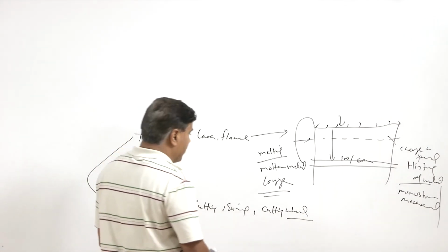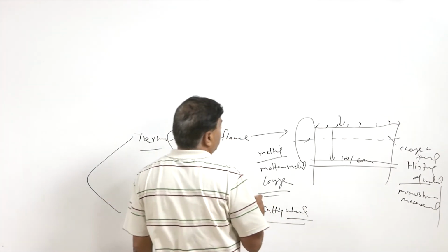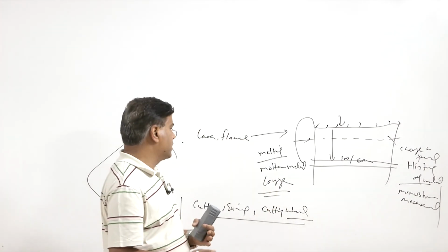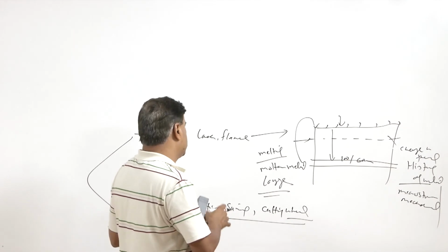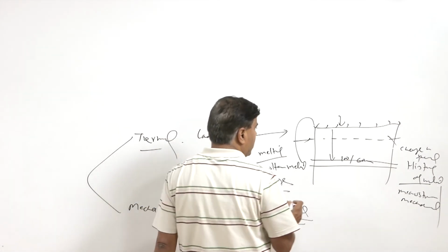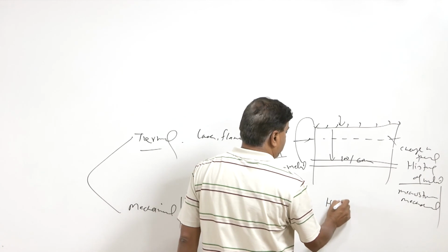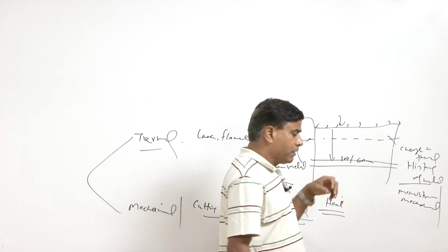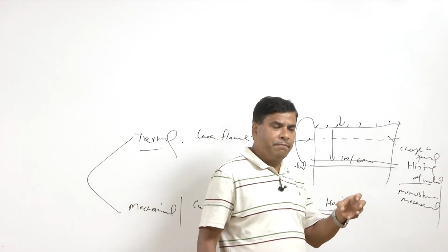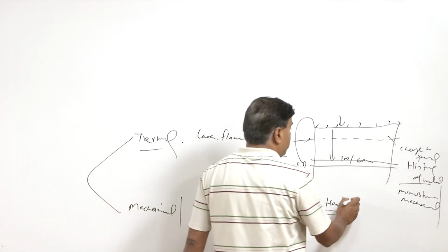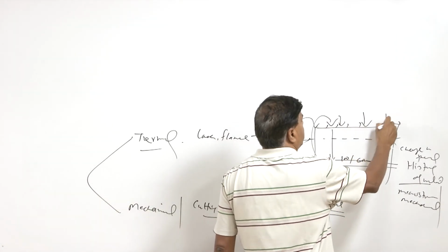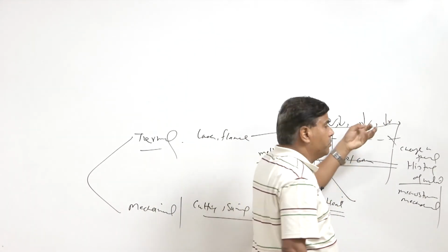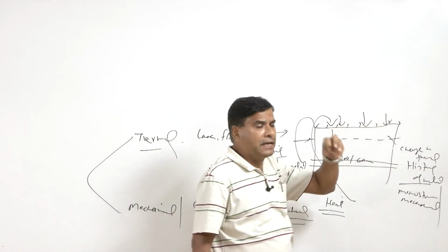In the mechanical method we can use cutter grinders or diamond cutters, or a hacksaw, or sawing can be done. But in all these cases also some heat is generated. In order to have good tool life, either of the blade or of the cutters, we normally apply cutting fluid. If the cutting fluid is applied, it can also modify the chemical history of the component. It may cause rusting, and it may cause the presence of additional cutting fluid which might not have been there at the time of failure.